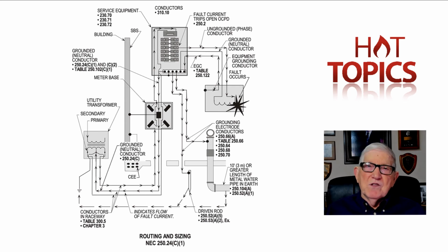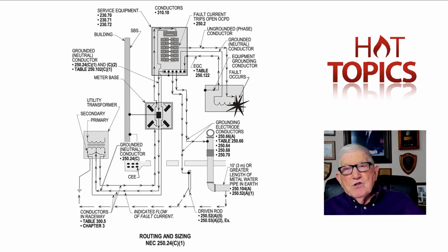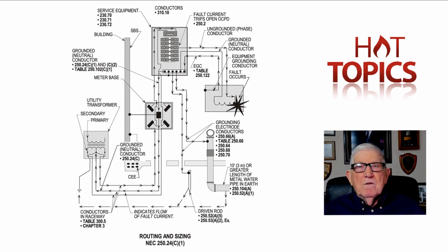And we have to size it by 220.61, as I just previously pointed out to you. So page 38 defines the neutral and the neutral point, which is back here at the transformer. That's your neutral point.